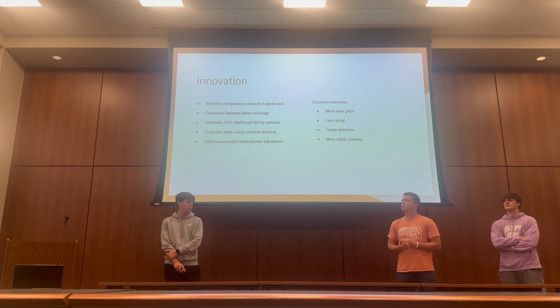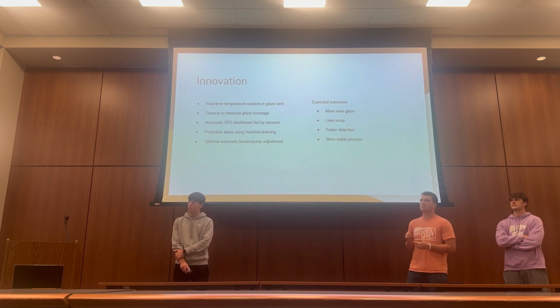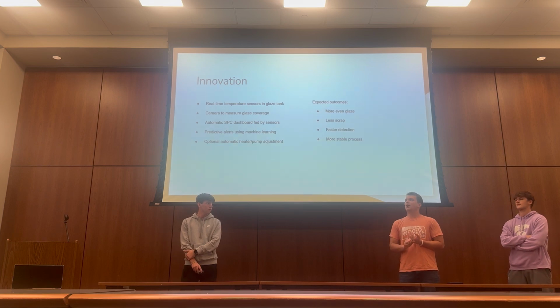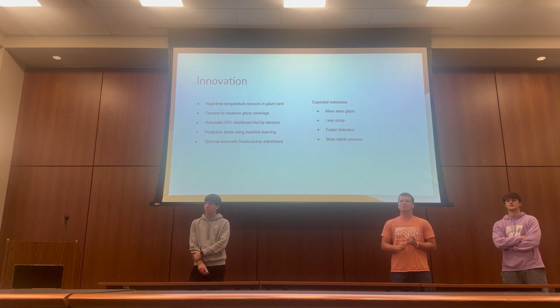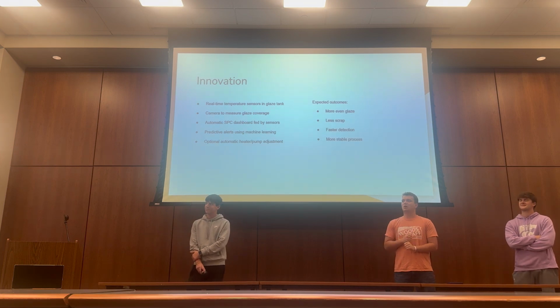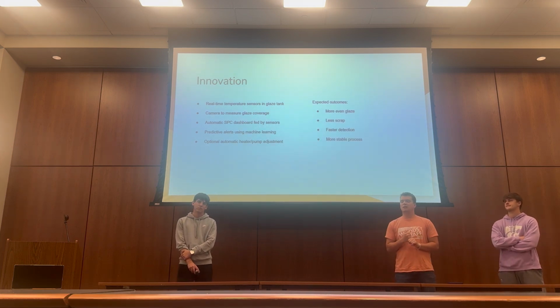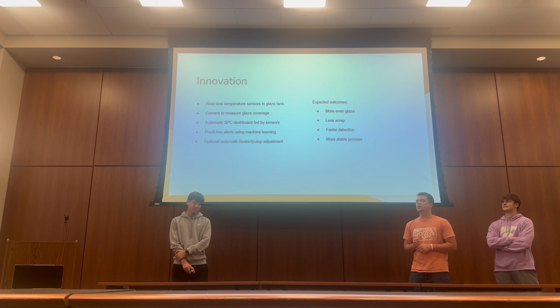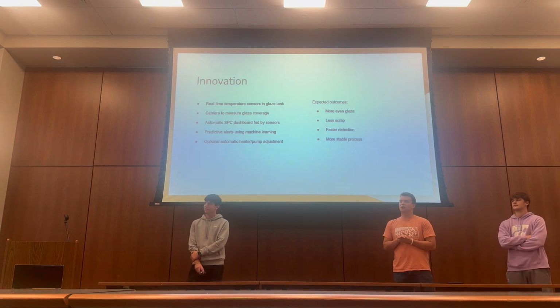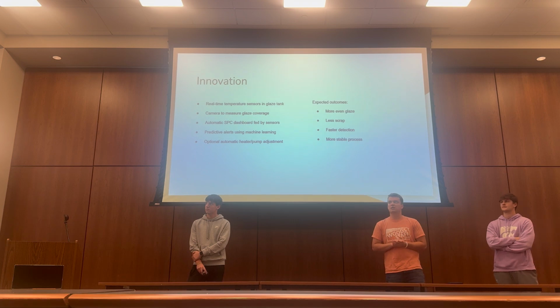Some of the innovations that we think can reduce that cost are real-time temperature sensors in the glaze tank, a camera to measure glaze coverage, an automatic SPC dashboard fed by sensors, predictive alerts using machine learning, as well as optional automatic heater and pump adjustment to further increase that quality. We expect a more even glaze, less scrap, faster detection, and an overall more stable process.